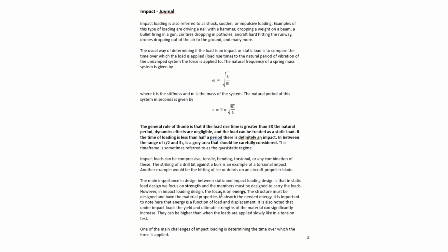It's also noted that under impact loads, the yield and ultimate strengths of the material can be significantly increased. The load is applied so quickly that the material essentially doesn't have time to respond, and those values of ultimate and yield strengths can actually be quite a bit higher. So this kind of gives you a little bit of a background on impact loading.